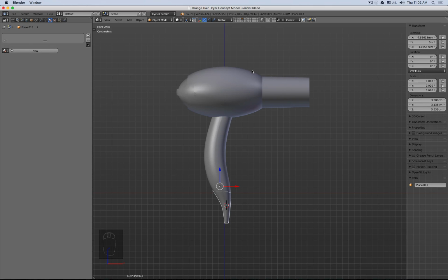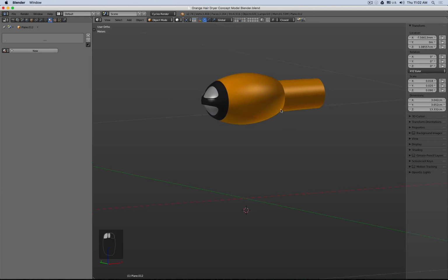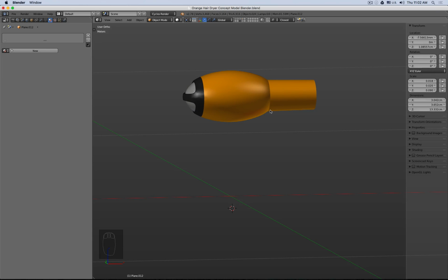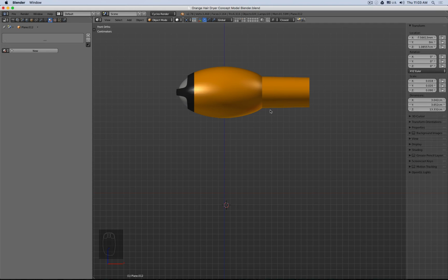So this was basically now everything we can do and should do in Blender. So we sculpted the nice handle easily the way how we need, and then we used the Boolean command with the carve library and surface test to quickly split the design, and then also give on an object basis some materials to see how this maybe could look like, because now it's easier to understand maybe the size, volume, the weight of certain elements.